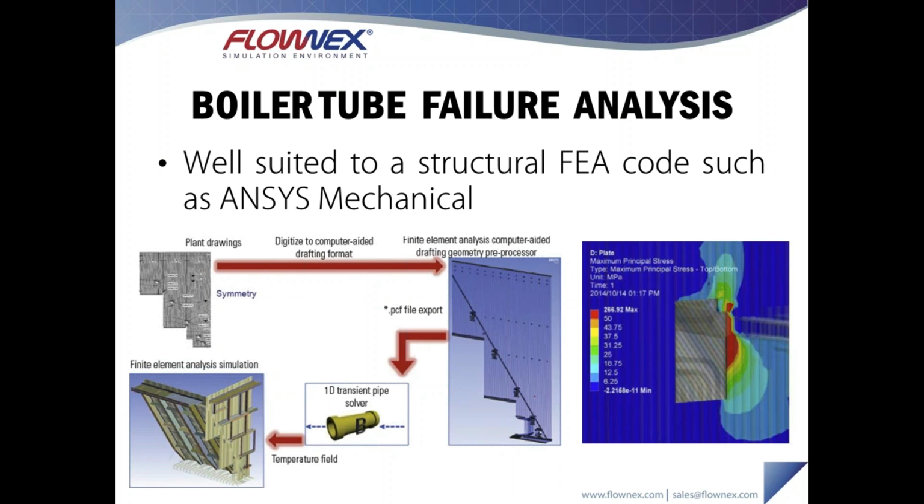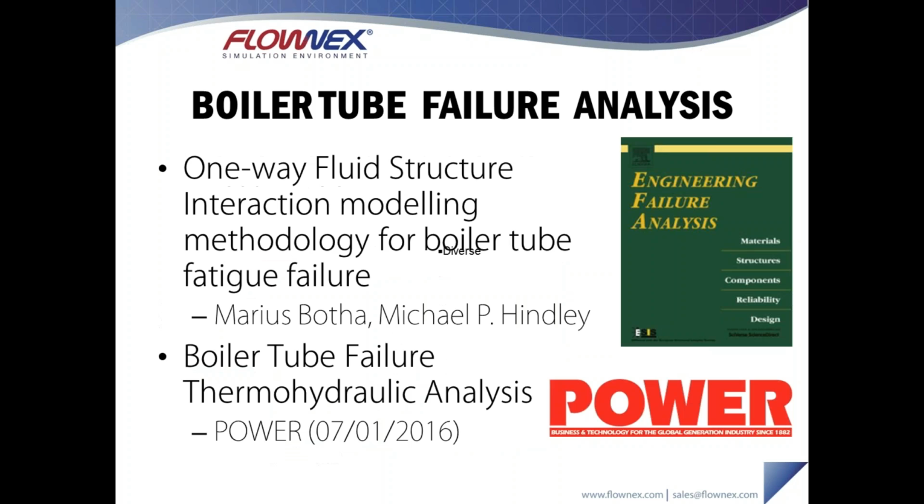This led to quite interesting results. Basically, engineers were able to identify these high stress zones inside of the boiler and make small modifications to the geometry to minimize these stress concentrations and basically reduce the likelihood of the boiler tube failures.